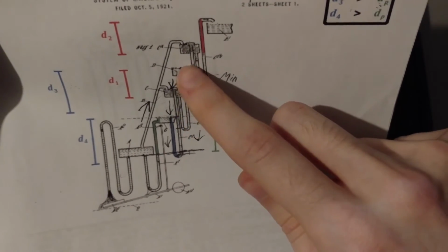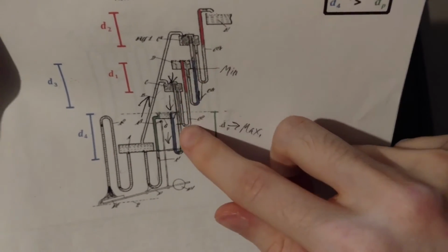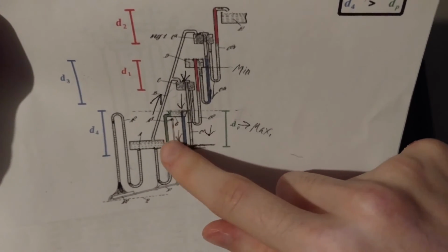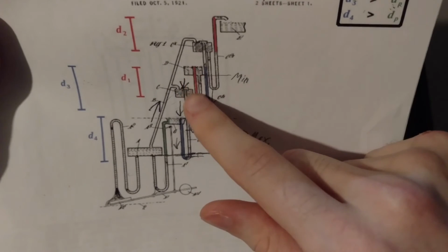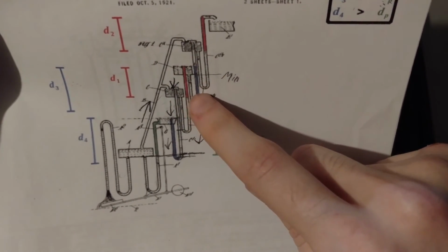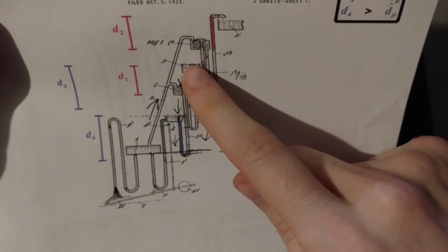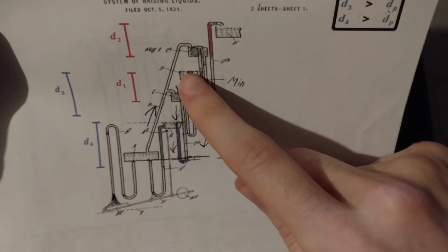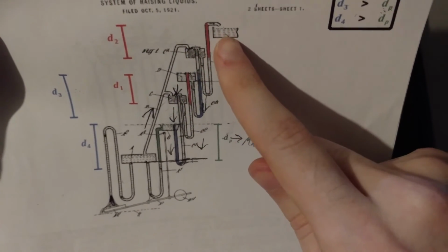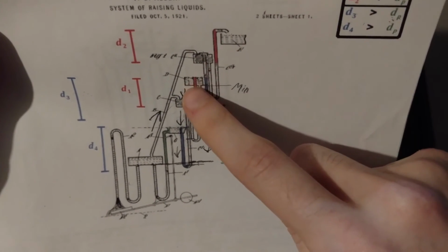That maximum back pressure always has to be less than the pressure that's generated by here. Otherwise, like before, it's just going to stall out. The pressure here is going to be too high for the water to be pushed up past that pipe and into the open containers here, this reservoir and this other open container here.